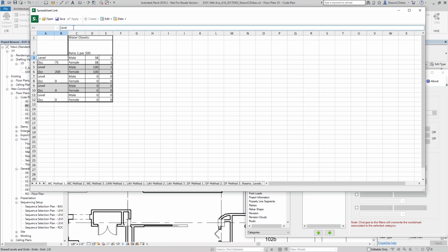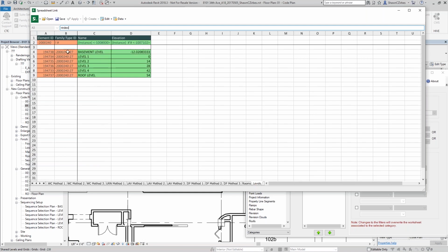So I can go into here and do what's called either a VLOOKUP or an INDEX, or a lot of different things. I'm going to use the INDEX command. I'm going to index an entire list of things, okay? I'm going to index the entire levels area over here. I'm just going to grab a bunch of them. I don't really care. You can go 100 levels if you want to. If you commonly do 100, you can have this thing pull from the full list.